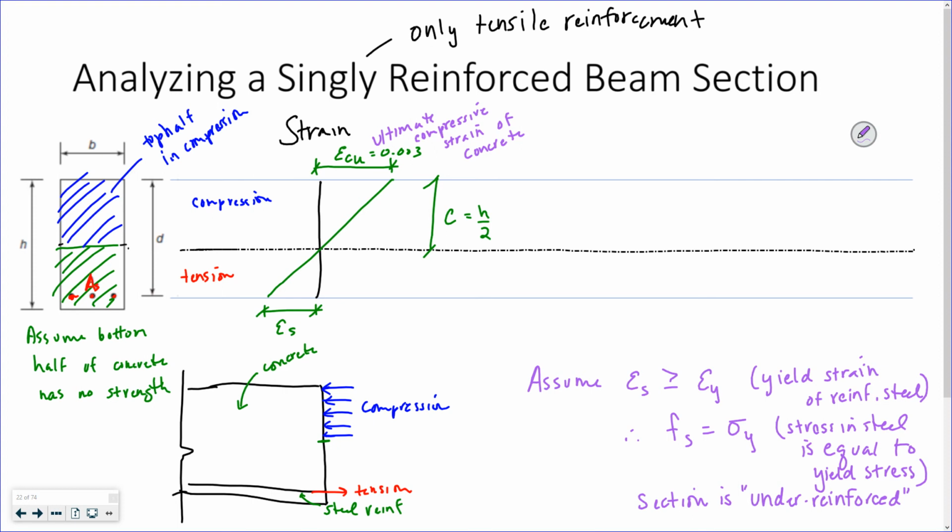It means compared to the concrete, you're gonna fail your steel first, and you want to fail your steel first before you fail your concrete. That is what it means.